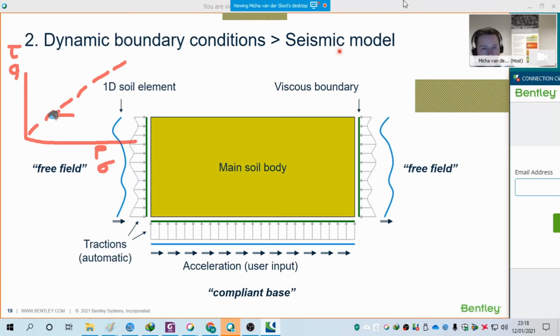Now this can happen when we have low stresses in frictional materials, or when we generate excess pore pressure on the boundary. And then we can also have this effect that, because we develop excess pore pressure, so I should make sure this is effective stress and effective mean stress, we can also then get into this point. Now, the key in this is that it might not be that bad that it happened, because with plasticity we will have damping there, so that means that the wave will not reflect back into the main domain. It will go here, it will lose its energy, and it will not come back into the main domain. So if you put your boundaries far enough away, it will not have an effect on the main domain.